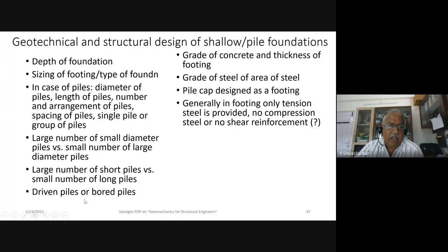So if you use a group of piles, there is pile group interaction. That is, we have group efficiency, we have interference of piles. Incorporating all this in the soil structure analysis is really difficult. Finite element itself is an approximate method, and we make further approximations. As I said, our aim is to predict the load carrying capacity and the settlements as close to reality as possible. So whenever our inputs are more real, then only our output also will be real.